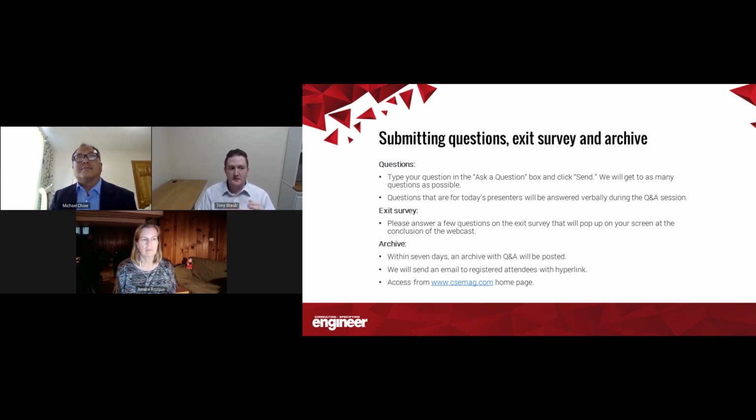But then there's also that humankind tends to feel a little bit less comfortable once you start to get to a really high color temperature, 5,000, 6,000, 6,500 Kelvin. So I see 4,000 Kelvin as a really great compromise between good perception of brightness and comfort. And that's where I'm shooting for.